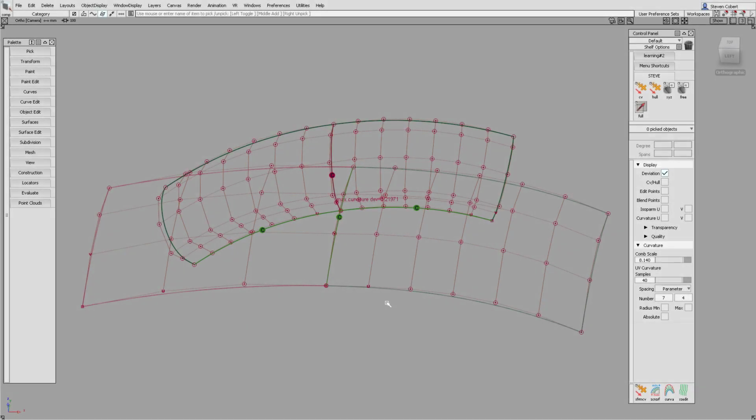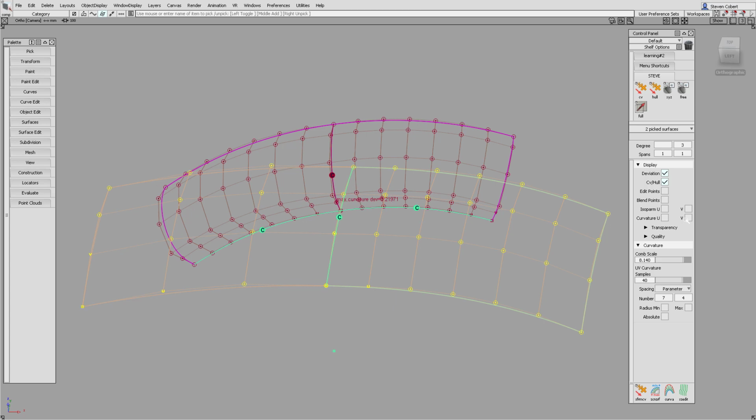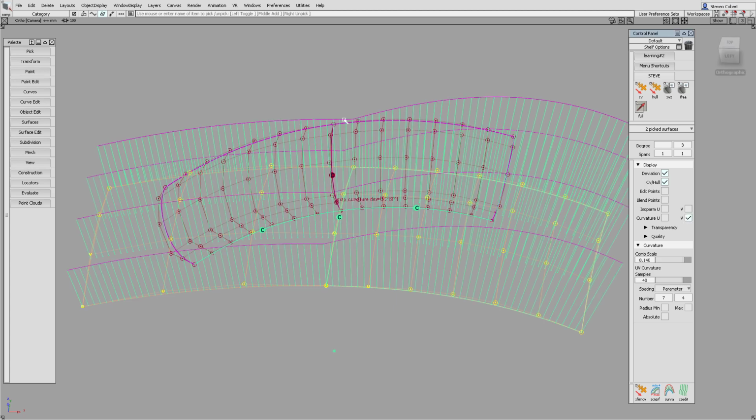Now this is an example where we haven't been able to achieve curvature at this edge, but we've got curvature on all of the other edges. What's worth trying is seeing if we get this to G3 continuity, whether that helps. So let's have a look at those surfaces. So we can see the curvature comes along, it's G2 continuous, but then it comes off at a different angle, showing that we haven't got G3 continuity.